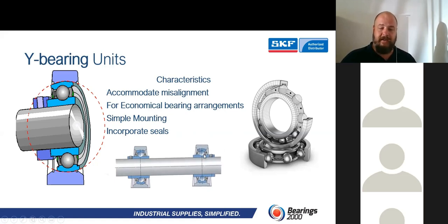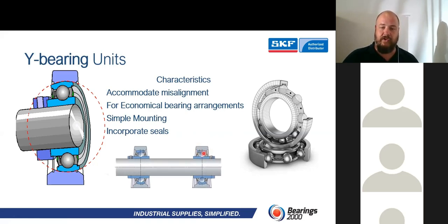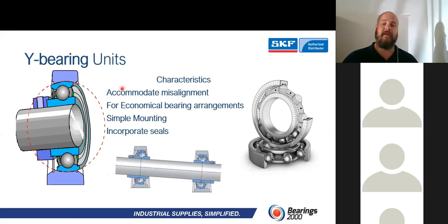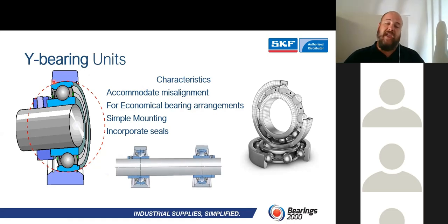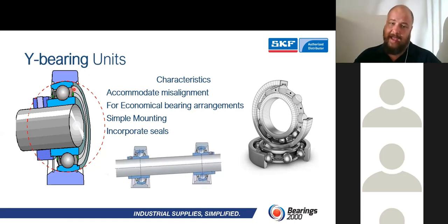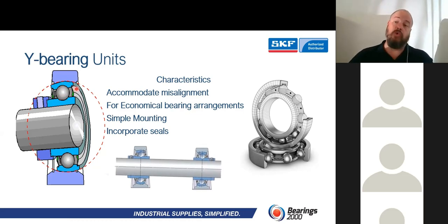Okay, having a look at what they do, that is actually how these units work. And as you can see, I've just put my little laser pointer on there. As you can see, it moves within the housing. But the ball bearing itself, the deep groove ball bearing, does what it needs to do. Okay. Being a ball bearing and having these integrated seals, you do not get the same speed out of them. So they are also limited.